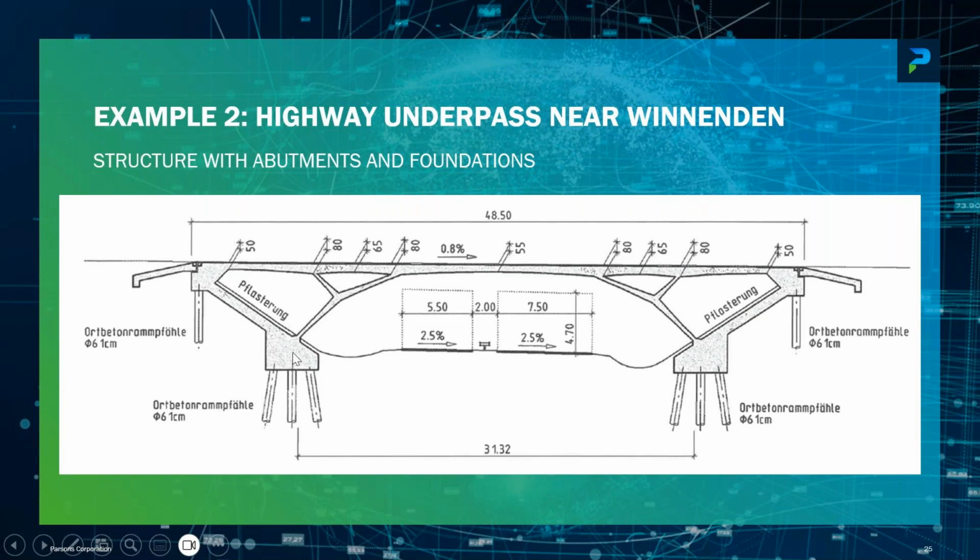And that's exactly what happens on a cable-stayed bridge, and that's why you have the anchor piers and the anchor cables. So I don't have anchor cables here, but I have anchor piles. Those piles will see no tension under SLS conditions, but under ULS conditions, and that's why they are important, because they help to increase the stiffness for vertical loads, but they are not increasing the stiffness for horizontal loads. So, for example, these piles are very flexible and the bridge can still nicely expand and contract, but it's still stiff for vertical loads. And this is performance-based design. You build your structure so that you get the performance you want to see in the structure.